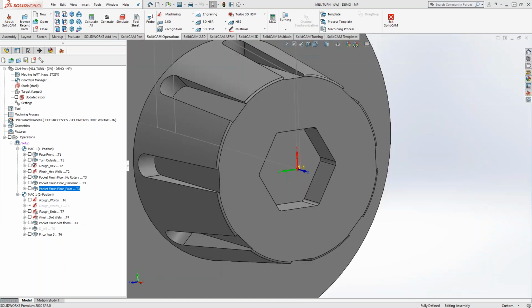Yes. So the idea is that if you have any kind of CAD data, you can import it inside SolidWorks, translate it into SolidWorks geometry, and then you can use it. So if you have a point cloud, yes, absolutely, you can do that. Now, what you can do with that after you've imported it is either turn that point cloud into surfaces if you have that ability with your SolidWorks, if you go that far into doing surfacing. If you are just using point cloud data, as in it's a bunch of vertices of your solid, you can do that as well. You can use define by 3-point associative.